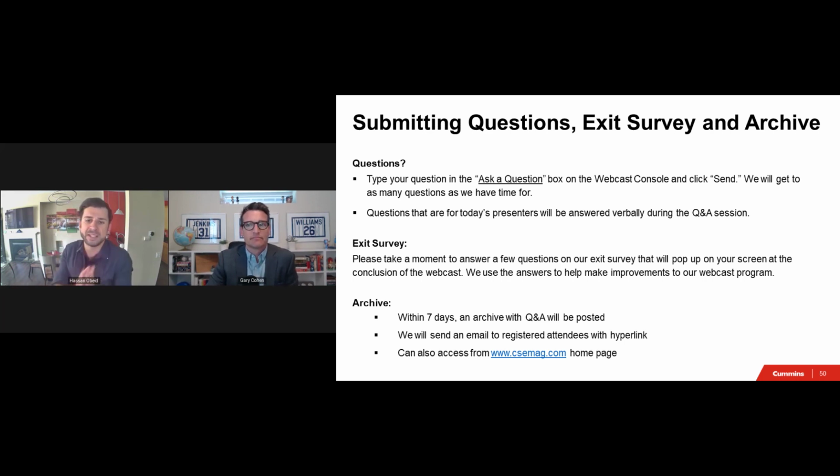Because if I can handle 100,000 amps for 3 cycles, I can definitely handle 100,000 amps for 1.5 cycles. So I think this is what the question was asking. But if not, please send it again, and I'll be happy to address it on the CSC's website.